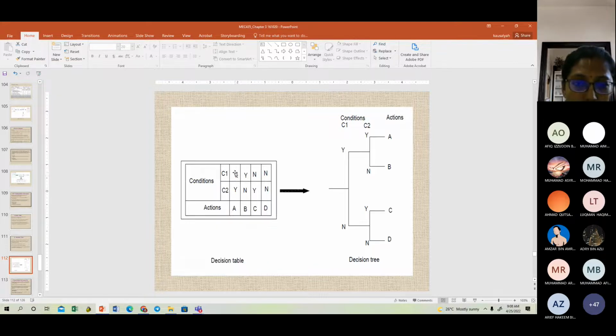So based on your cutting speed, you need to switch on your lubrication, you will say yes, yes, all right? Referring to a different cutting speed, if you do not need your lubrication, then you will say no, all right? If there is no movement in your tool, as in no cutting speed, should you have your lubrication on? You may want to, just to cool the environment, then there is a yes. If there is no cutting, no lubrication at all, then no.